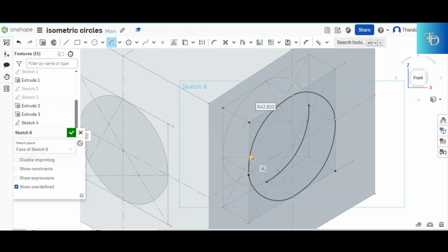Now pay attention. You cannot place your compass at that center and then outline all the way from that point to that point. Why is that? Because you cannot see the inner part of the circle from here. You can only see where it ends. So you place your compass there, you open it up to there, you only outline from there. Just like that. And then the next point, whereby you are using that center right there, you outline from that point, and then when you meet the outer circle, that's where your compass stops. This is how you represent the depth of a circle.